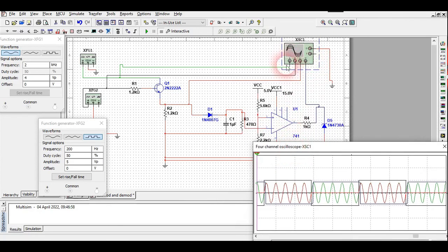In the 2-channel oscilloscope, we got the red output when the bit was 0, okay. Now just look at this violet one. This violet one and this black line are basically the same signal, okay. This black line is the input signal and this violet one is the demodulation part. But both are inverted. Why are both inverted? Because we have used the op amp in an inverting configuration, okay. So we are getting the output as a violet line only when we are getting this red signal, that is our modulation output, okay. So this one is bit 0 only, okay.